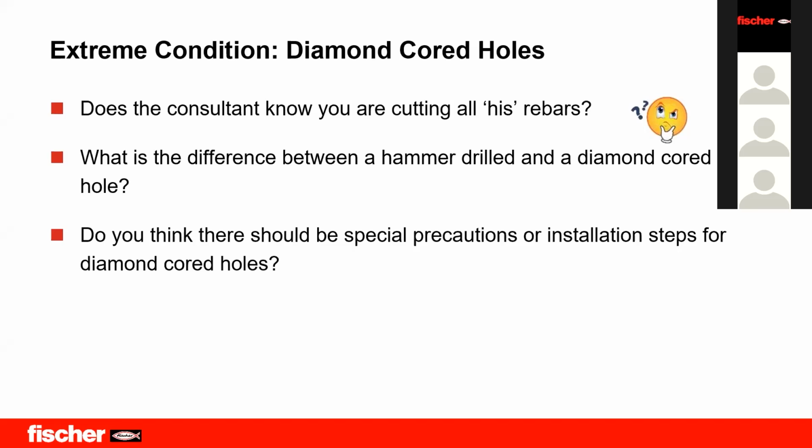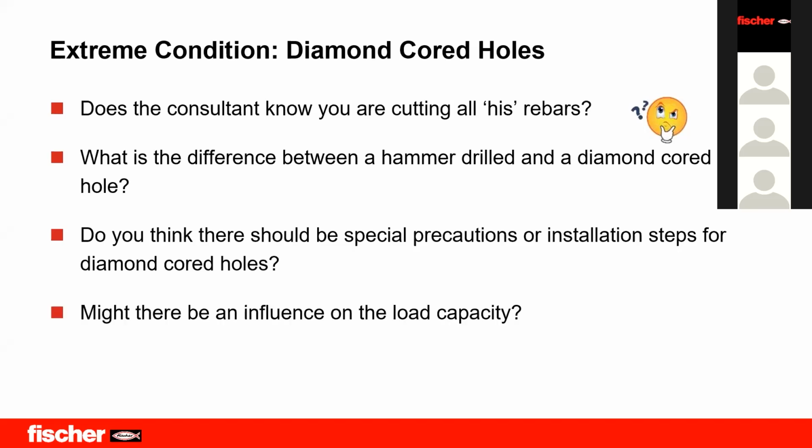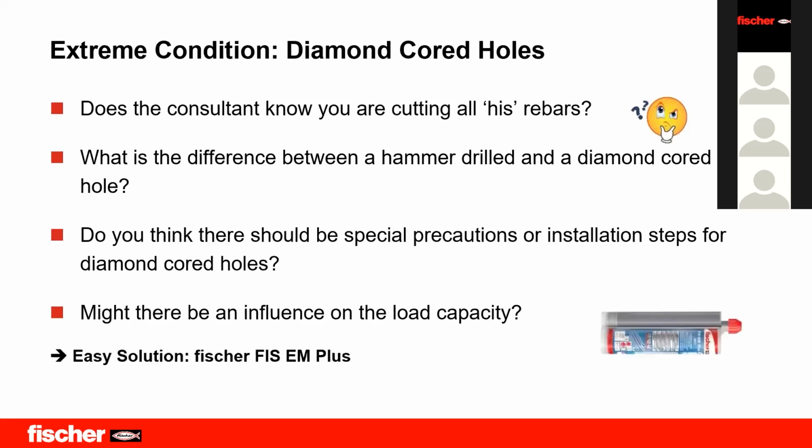The elaborated installation steps are shown in the ETA, because there is a slight change in cleaning procedures, and also whether it has an influence on the load capacity. But for all these conditions, we do have a solution, known as epoxy mortar plus, FIS EM Plus, which has 120 years of service life. It's used in water applications, has all the approvals like seismic, fire, ICC, and is approved for diamond core drilling as well as hammer drilling.